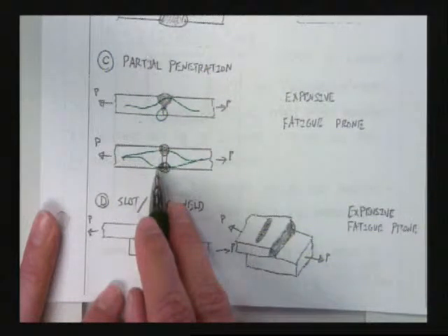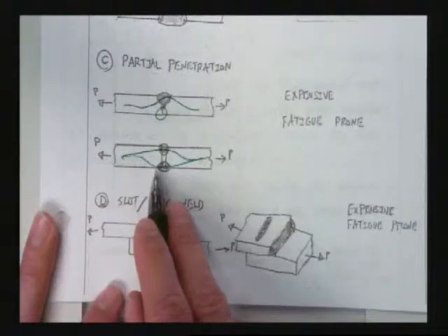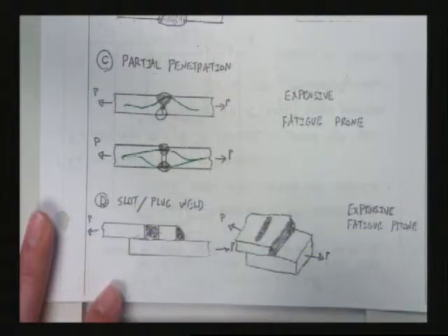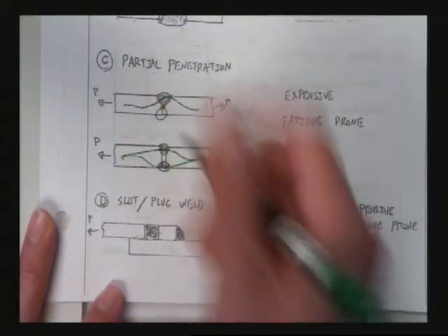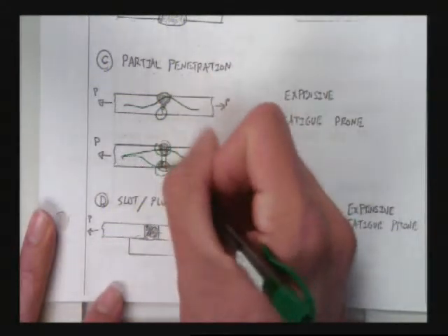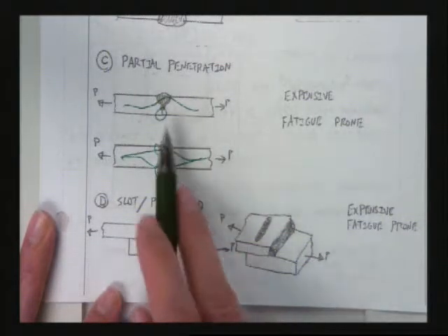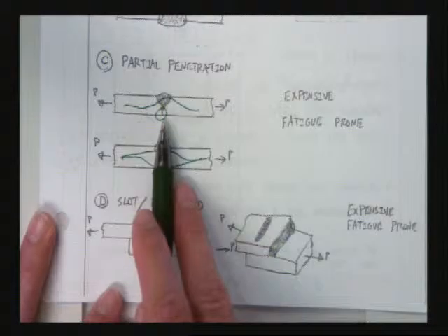Whenever we make load move, you're going to create stress concentrations, okay? And when you get fatigue issues, that's where you'd expect to see the failures, locally around these welds, fatigue type failures. But that doesn't mean we can't design these safely, okay? It can be done.